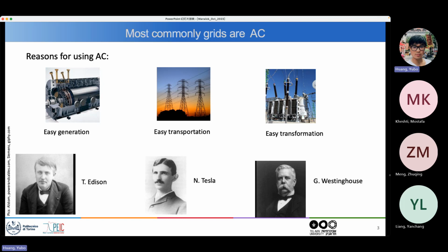It doesn't blow up if you are careful, because if you connect them at a wrong phase angle, you get a huge current. But if you connect them at the correct phase angle, they remain synchronized. After that, you can do all kinds of perturbations on the system, like load changes and priming torque changes, and they remain synchronized.